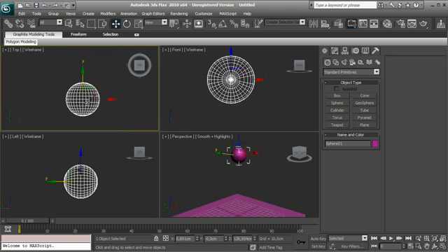To create the fragments manually, we use the ProCutter feature coming in 3ds Max, and for this tutorial we'll use 3ds Max 2010, as you can see. This is a way to create the pieces, but you can also use the Boolean feature or the ProBoolean feature, using maybe not a plane to cut the mesh, but a three-dimensional mesh to make the Boolean.